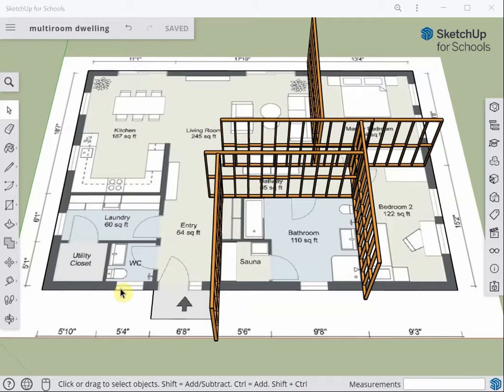On the floor plan, I can see in my drawing clearly where doors are, and this symbol here, the white rectangle with the line through it, indicates where windows are. And the first thing you'll notice, looking more closely at this floor plan, is the internal walls are notably thinner than the external walls. Okay, and that's typical in a structure for the external walls to be double walls. So we'll cover that a little bit later. We're going to do a timber internal wall and then an outside wall which will be made out of brick, which is what we call a brick veneer construction.